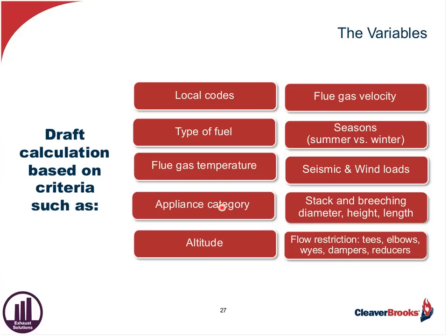What about the altitude? What's the altitude going to do for me? Well, as we go up in elevation, of course, the air becomes what? Less dense, right? So this impacts my pressure density differential and the ability of my stack to pull the proper negative, if you will, and be able to vent properly. So altitude is a huge concern as well. If I'm at sea level, I don't worry about it. But if I'm in Denver, it's a major concern.